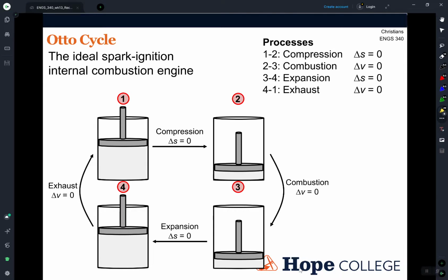This is the standard internal combustion engine where we have a spark ignition. So we would have something like this where going from what I have labeled 1 to 2, we have our compression process. Then from 2 to 3, our piston doesn't move, but we have a step in terms of the thermodynamics, and that's where we have what essentially is an instantaneous combustion because we have our spark plug, which sparks the air-fuel mixture and causes it to combust, to explode.